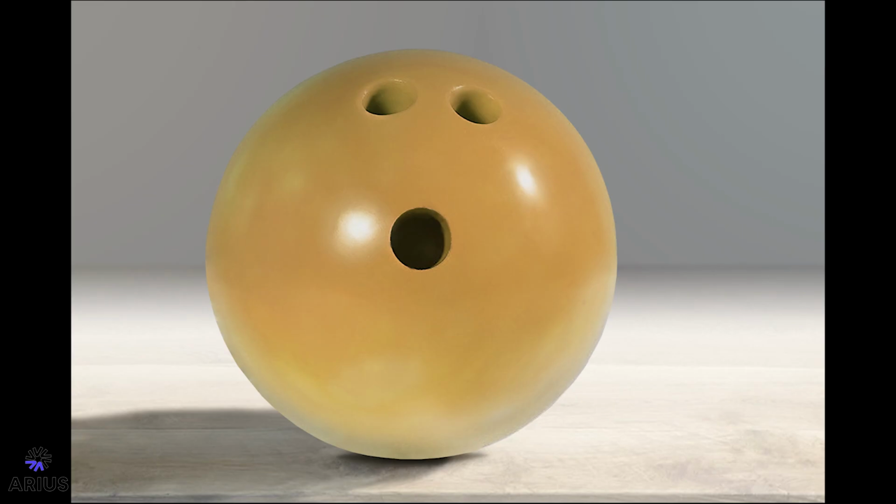Often, the color image is used as a starting point to generate a grayscale elevation file, or to add fine details in the sub-millimeter range. When this image is converted to grayscale, the orange of the ball becomes an undulating dark gray, with the gloss specular highlights staying white. If this grayscale image is used as an elevation file, these specular points, when surrounded by darker pixels, will become divots in the ball's surface. And conversely, these black and dark parts of the finger holes would spike up off the surrounding surface.